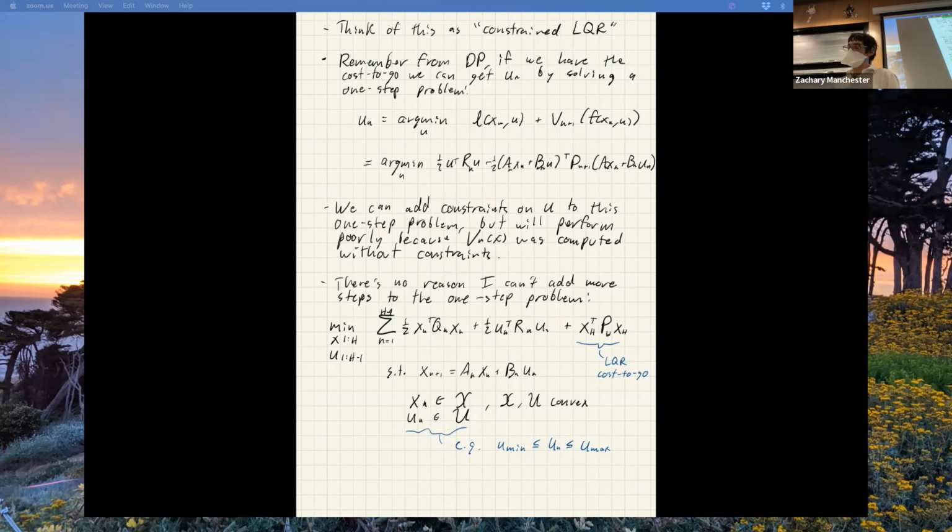The way to think about it, these constraints are things that you don't get to choose. They're things coming from the hardware, right? That you want to encode in the controller somehow. Think of them in the same vein as the dynamics, right? They're part of the system model. In the case of actuator limits, they're really part of the dynamics, right?